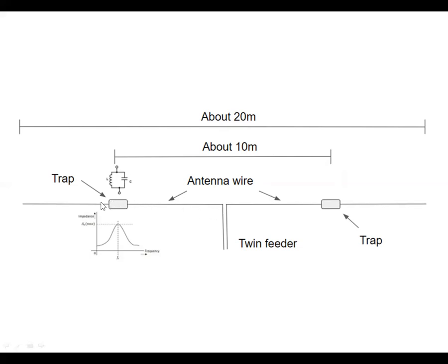But then as it gets higher in frequency, the impedance goes down, so it becomes almost a short circuit. Essentially, if you're sitting in this element and looking this way, you see this trap circuit, and when you're at 20 meters, it looks like an open circuit. So what is an open circuit on a dipole?